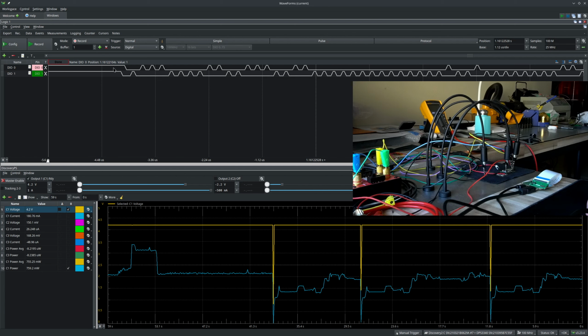So there's this characteristic escape mode entry here, which ends right about there, and then this is least significant bit first. So from MSB to LSB, it's 11100001, which is the low power data transmission entry byte essentially, and then from there on you have data.